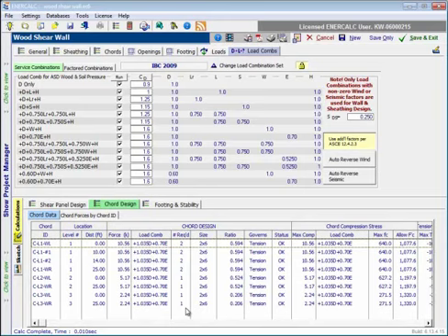Remember, all the way back to the chords tab, what we entered was the size, the 2x6 size. But the program is actually determining how many 2x6s are required at each location. So if we envision this as an upside down building, we can see that at level 3 and at level 2 we only require one 2x6, but when we get down to level 1 we actually need to double them so that we have two 2x6s at each and every chord location in this wall.